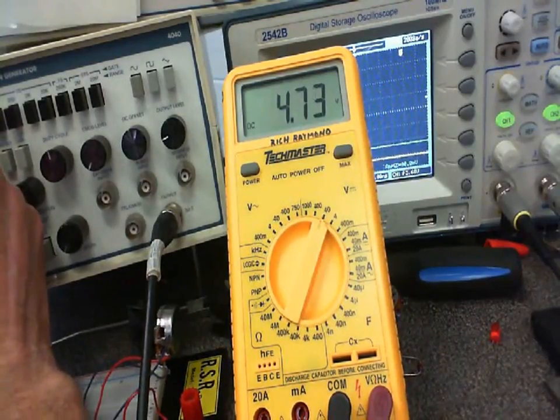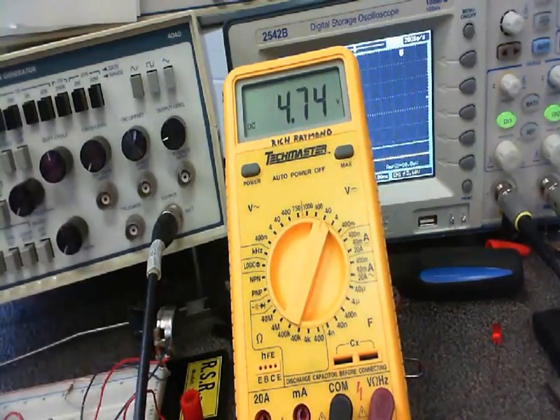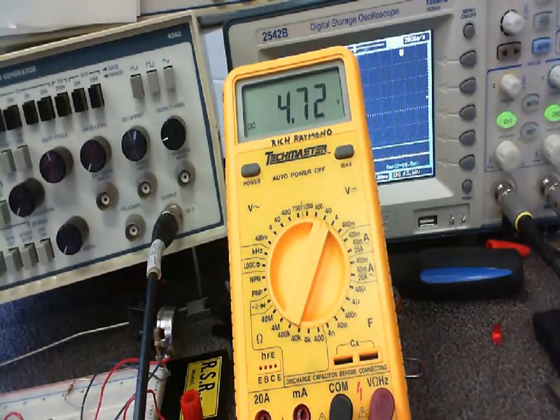I can touch this. We got plenty of these. So the problem is when we start dealing with beta, we have a problem with temperature, right? You understand that? So if the temperature goes up, then what happens to beta? It goes up, yeah. And if beta goes up, then IC goes up. If IC goes up, then the voltage drop across the transistor is going to go down, and then the voltage drop across everything else is going to go up, right? Because the amount of IC you have determines the amount of resistance that the transistor has.